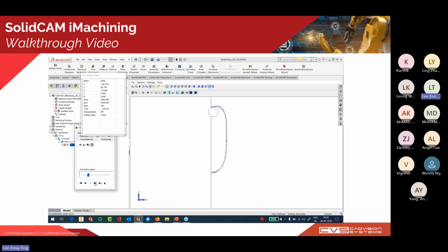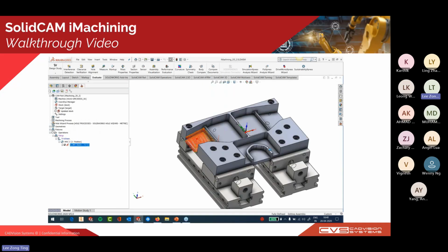And by varying the feed rate, you can eliminate those slow movements, and it can greatly reduce the machining times for this specific part. So just now we said that iMachining will read the material properties from the material database for the material we choose.